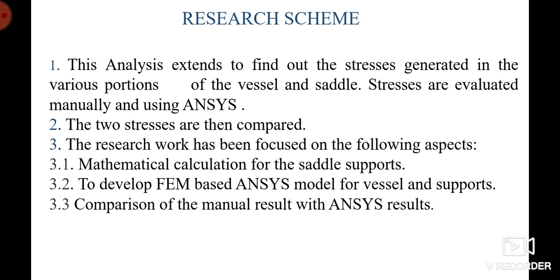Research scheme means what are the schemes that we need to consider, that we need to evaluate after our research, our project is completed. So first of all, we will prepare a mesh analysis of the horizontal pressure vessel and twin saddle support in the ANSYS software, and some mathematical formulation will also be done.